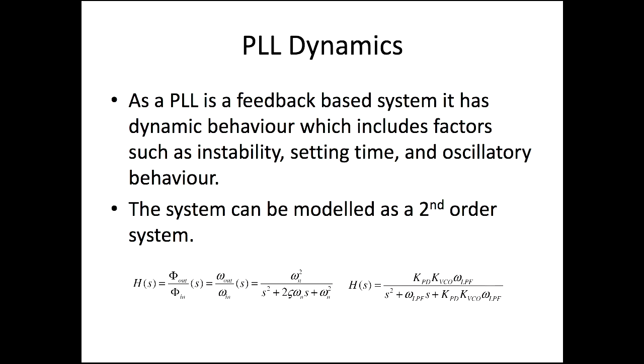It can't match it to that one. So when you take the data sheet, they will say what is the range you can connect. If the center frequency equals 1 kilohertz, they will say, okay, this PLL, maybe you can connect 1.5 kilohertz, it is fine. Maybe the 1 kilohertz will adjust to that one. So there is a locking range. You cannot have a big range. And then it is locked, unlocked.